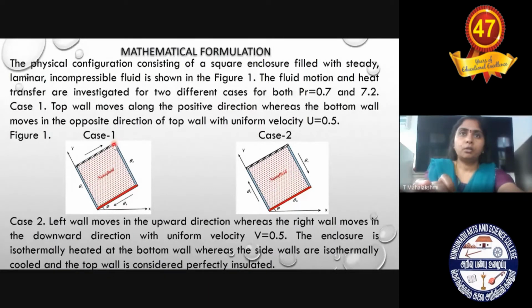Now you will be thinking about what is meant by adiabatic. Adiabatic condition is there in heat transfer analysis. Once we consider the adiabatic condition, it means no heat transfer will occur, so no transfer of heat occurs from the surroundings to the enclosure. So the top wall is considered adiabatic in both cases, the vertical walls are kept cold, whereas the bottom wall is kept hot. And the enclosure is inclined at different angles also.